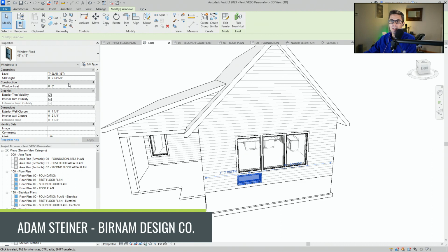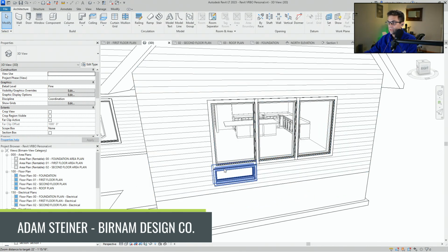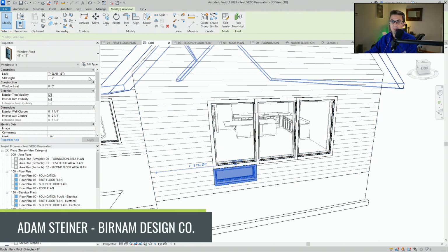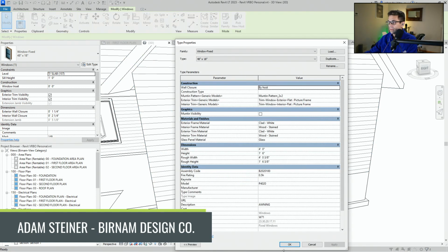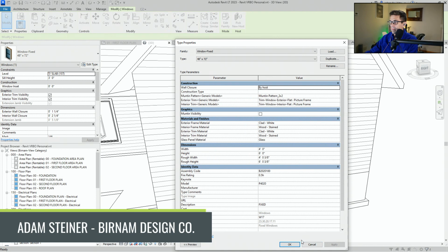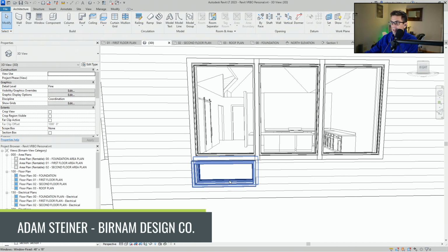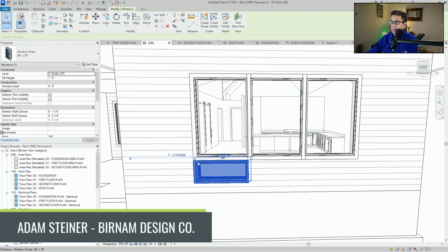Okay, now I'm going to come in and edit this. Sill height. Do we want 6 inches off the floor? No, I can do a whole foot, I think. Is that too much? Also, why aren't you the same width as the window above? That's 48. Is it just not aligned? Also, those window trims are different thicknesses.